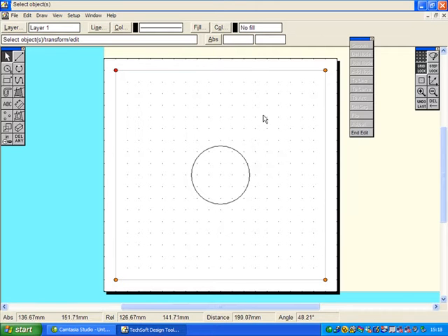Now what I'm going to do is click on an individual line at the top here, and you'll see that line itself changes colour to the pinky colour to show the line has been selected. Now if I come across to the selection menu here, Add Node, click on Add Node, you see an extra node in the middle there. I'm going to draw that down right into the middle of the circle we drew in the first place and just release the left hand button.